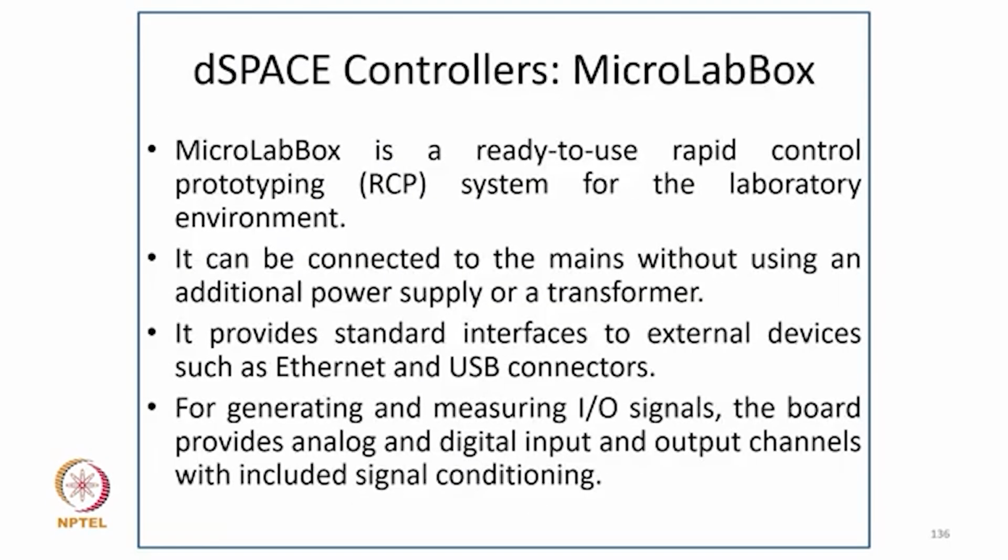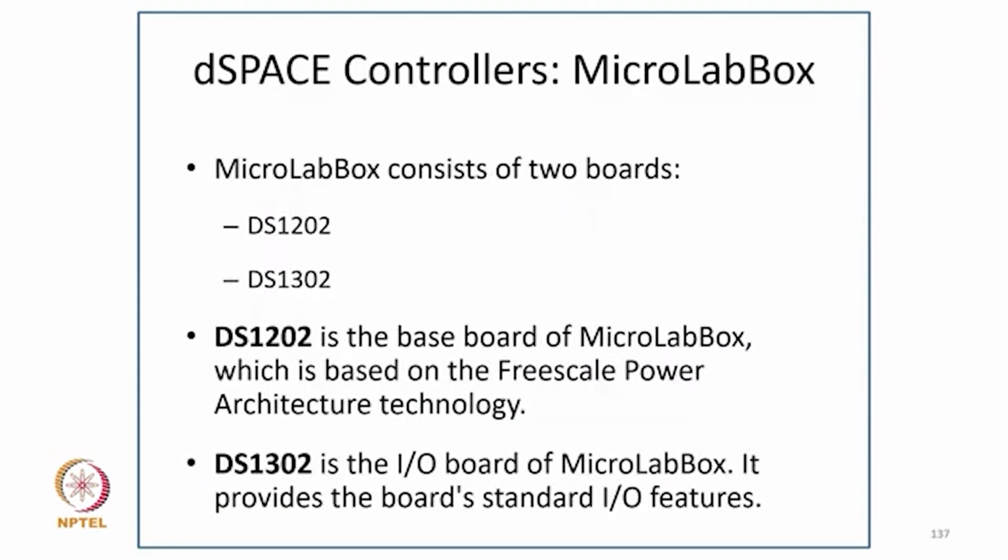So MicroLabBox is the next DSP controller by dSPACE. MicroLabBox is a ready-to-use rapid control prototyping RCP system for the laboratory environment. It can be connected to the mains without using an additional power supply or a transformer. It provides standard interfaces to external devices such as Ethernet or USB connectors for generating or measuring input-output signals. The board provides analog or digital input or output channels with included signal conditioning.